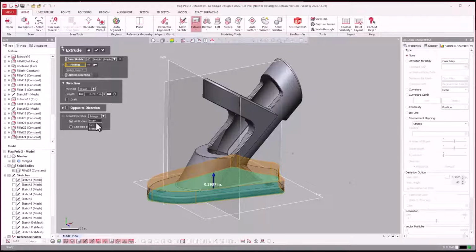If you go to SolidWorks, an extrude cut is a different command than an extrude merge. Those are two separate commands, where here that is one command. Or if you're in the Pro/E Creo world, you can't extrude and have more than one solid at a time. They have a very interesting rule there. Instead of having more than one solid at a time, you would have these bounded surfaces that you then use to Boolean or cut things away. So you have to get creative there.